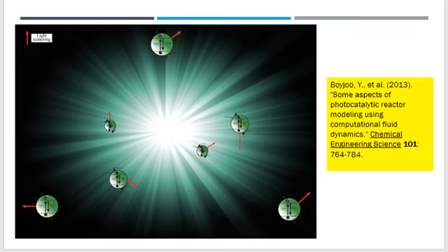The major issue with the slurry reactor is the catalyst itself, which exists as a solid suspension, which introduces scattering and absorption inside the aqueous medium. This causes the reaction intensity to reduce exponentially with an increasing amount of solid particles in the medium. Usually, the radiation is confined to a narrow strip and becomes negligible beyond 2 cm radius from the lamp assembly.